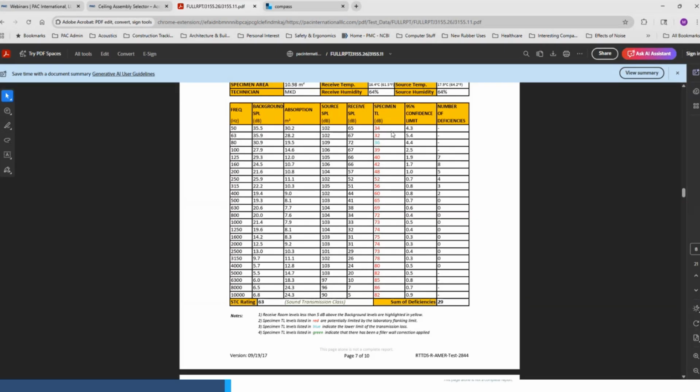But I think Intertech York stated the STC flanking limit is about STC 64 or 65. So if you're within 10 dB of the TL, the flanking limits, you flag it, right? So anything from like an STC 55 and above might start getting affected by flanking. And I see a lot of acousticians and folks recommending STC 65, STC 70, maybe even higher for